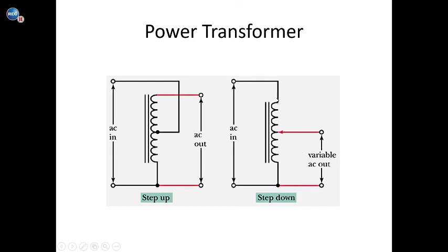And the primary voltage is applied to the full winding, and the secondary is taken out from the winding by use of a wiper. And so the wiper makes contact with the winding at some point. That essentially divides the winding into two separate windings, like two separate inductors. And we know that when we have two inductors in series, the voltage is divided between them proportionally to their inductance. And so the output voltage would be, in this example, maybe 50%, because the wiper is at about halfway through the inductor.